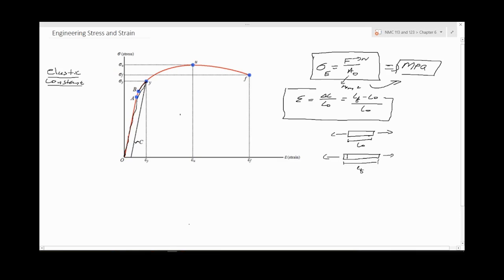The slope is mostly constant, so let me draw it at the top, something like this. This would be your strain, this would be your stress, and for the elastic region you'd have a constant slope until it gets to the yield point. And then you have a sharp turn there, and it continues. Here it's not particularly flat, but I think it was an experimental one, so that's why they use this solid black line. This is for what is called a 0.2 offset, but we'll discuss this when we talk about the tensile test.